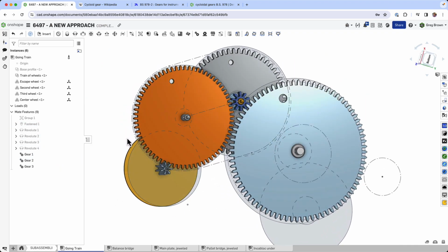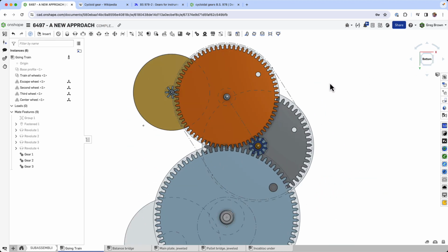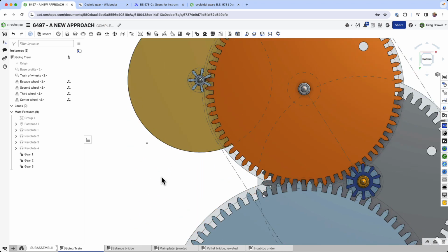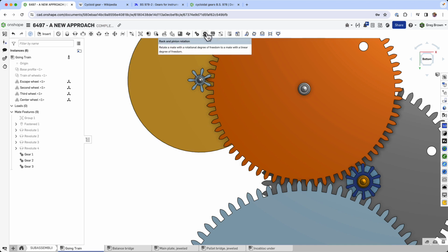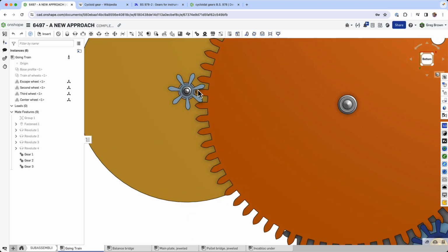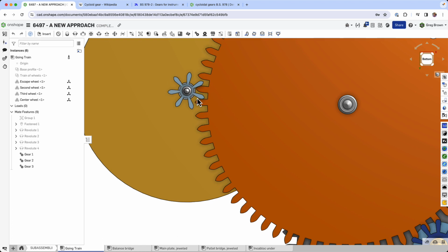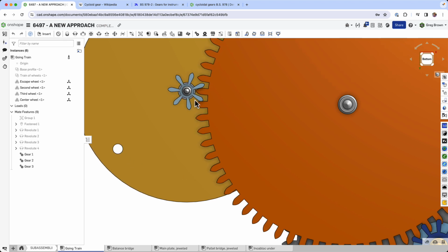subassembly like this. Now, the thing that you've probably all been waiting to see is the animations, right? So I'll turn off that. I have three gear relations. Gear relations are up here. I don't need a rack and pinion or screw or linear relationship. This is just purely gear relations. So that allows this beautiful meshing, and this travels. It's a clock. It's clockwise.